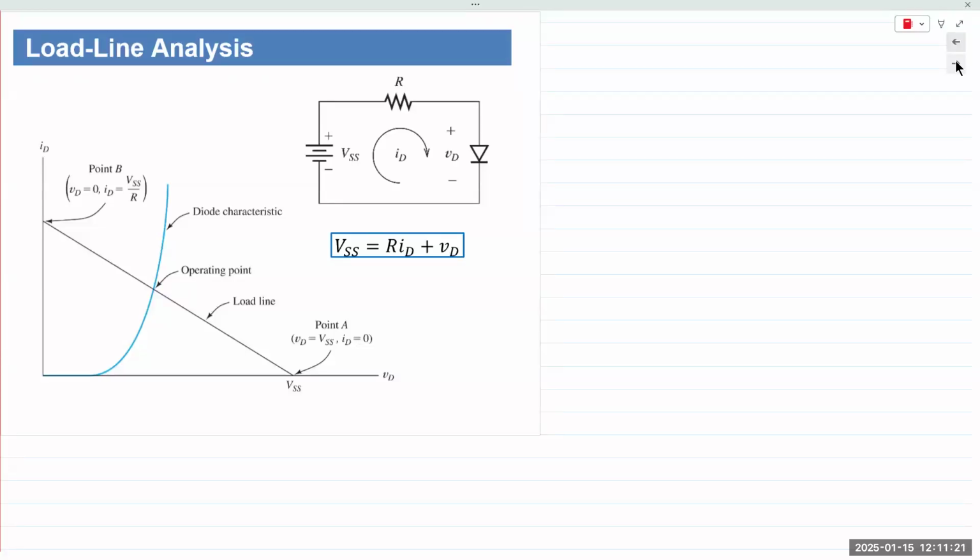Okay, there will be minor variations because the fabrication or manufacturing process cannot be controlled down to the atomic level. So even though two semiconductor devices are created at the same time, right next to each other on the same material, the properties would be different to a certain extent. For the most part, the variations are very small. So if you have, let's say, 4 diodes in your lab kits, the VI characteristic for all 4 diodes will be very similar. There'll be slight differences, but within a small range of values.